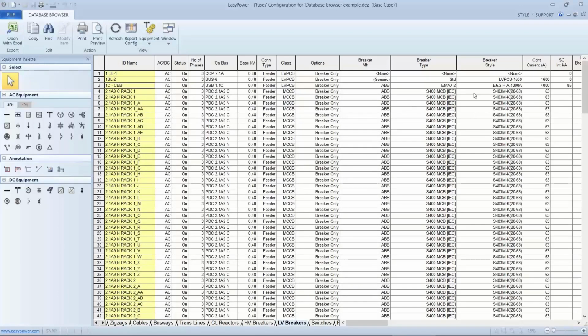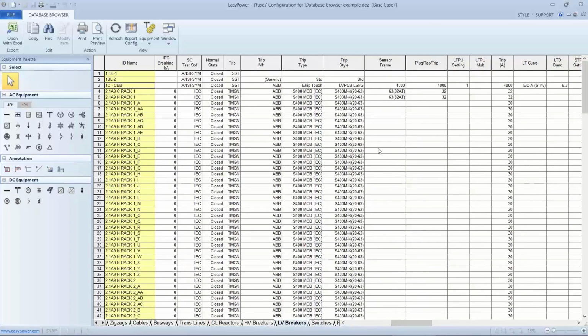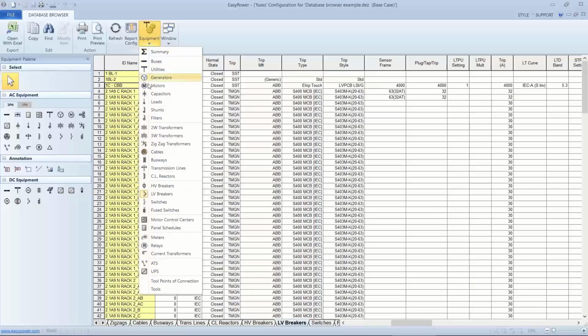So I have two issues. One is the part number wasn't set up. One that was set up, I didn't click calculate to make sure it was in the device library. And then it appears there's some issue with the device library that doesn't have this particular part number included in the ratings. Now, we've actually checked into this, and the issue is that the data in there shows that this is an IEC type of device, and consequently it won't have a breaker rating for that particular device for ANSI calculations. So again, that's being addressed. But at any rate, I've confirmed that's a holdup with my project.